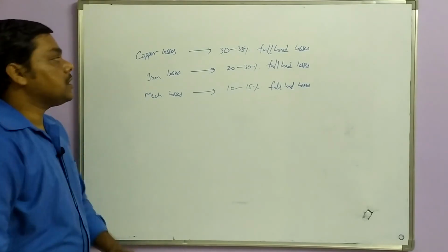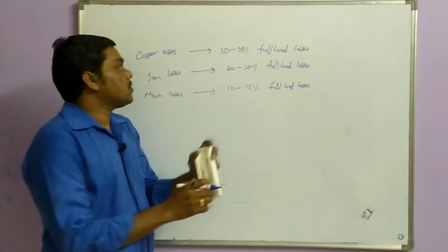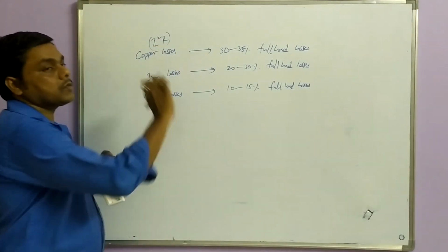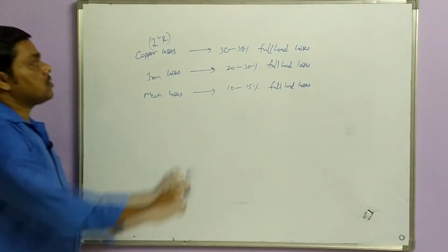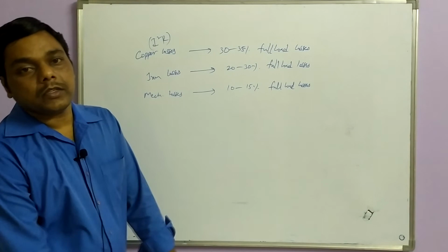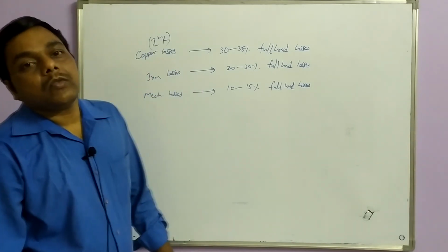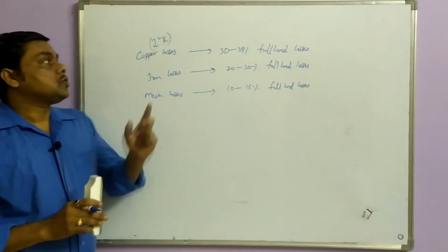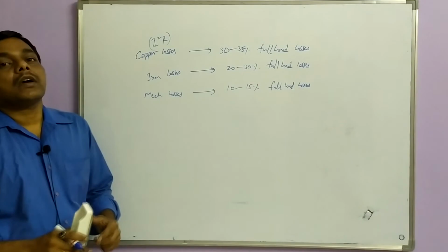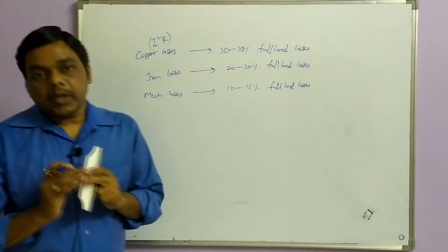Now we can see that these losses are due to electrical current. So what are the copper losses? Copper losses are nothing but I square R losses. When the current increases, copper losses also increase, since current is a square term. So keep in mind that to reduce the copper losses, the armature current has to be limited within the temperature limit.